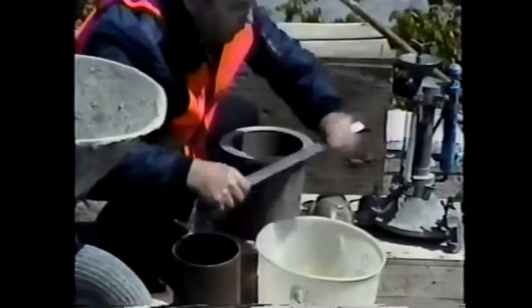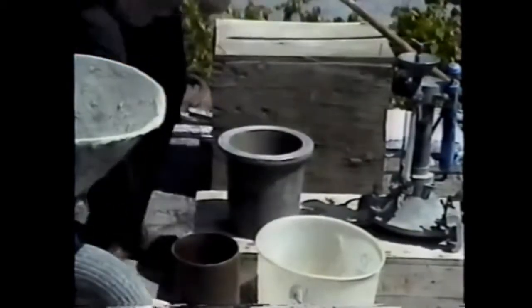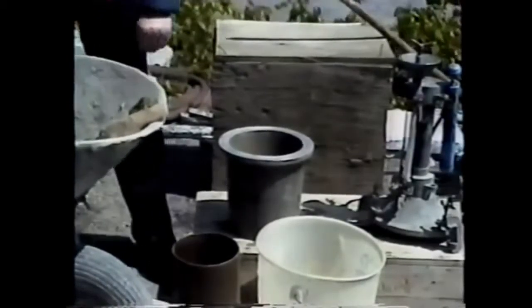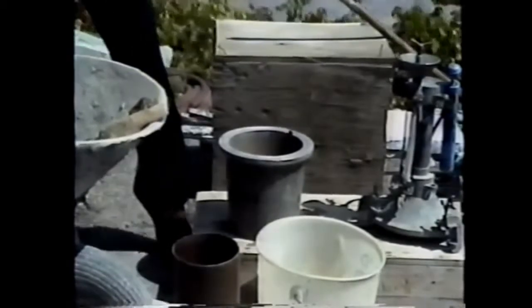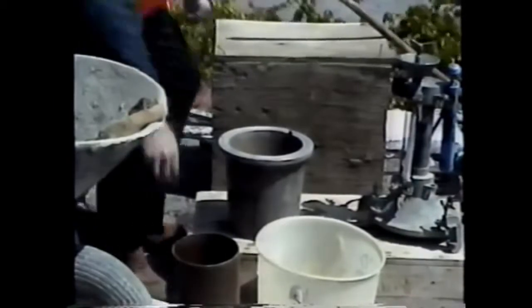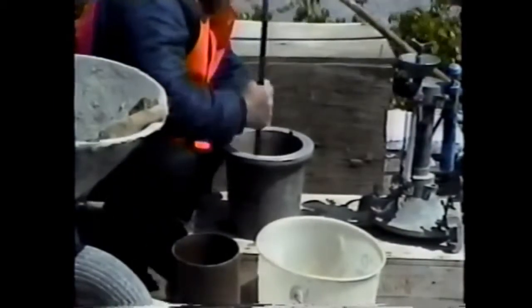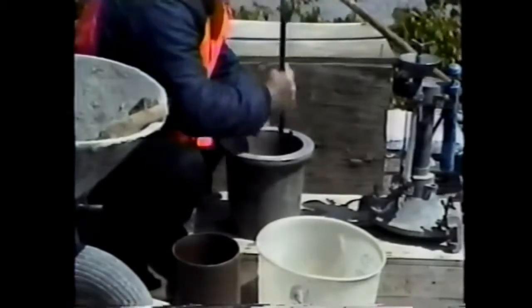As with the slump test, all the equipment should be clean and in good condition. It should be assembled near the concrete sample. The test is begun by filling the measuring bowl with concrete in either 2 or 3 equal layers and consolidating each one. The number of layers depends on whether the consolidating is done by rodding or vibrating.